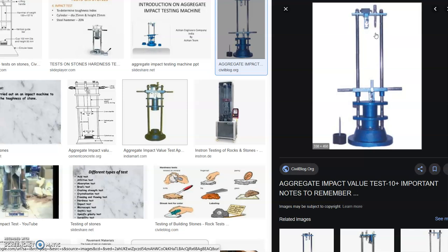increasing in the intensity. But impact loading is the sudden application of a very large amount of load for a shorter period of duration. So if you take a road, for example, if you make a small strip from the road surface, and if you see that strip alone, that strip is being subjected to a very high impact load coming from the vehicle. So for a very small period of time, in a microsecond, the vehicle will pass through, but still the load put on that strip of road is very high.